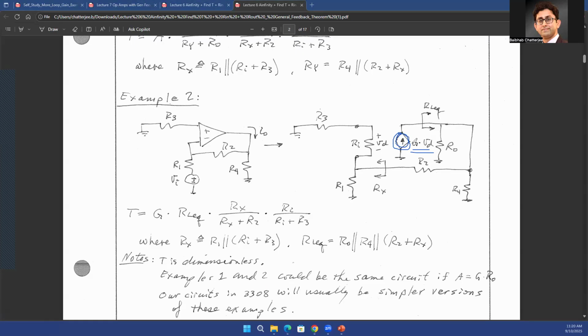A dependent current source, and the value of the dependent current source is transconductance G times whatever voltage you have at the input. So again, whatever voltage you develop across the Ri resistance. G times the voltage developed across the Ri resistance, that would be your current at the output of the model over here. And as you know, any current source should have a non-ideal parallel resistance. In the ideal scenario, it would have been infinitely large. But in a real scenario, Ro will not be infinitely large because this is the parallel resistance to a current source, which will be a finite value in the real scenario.